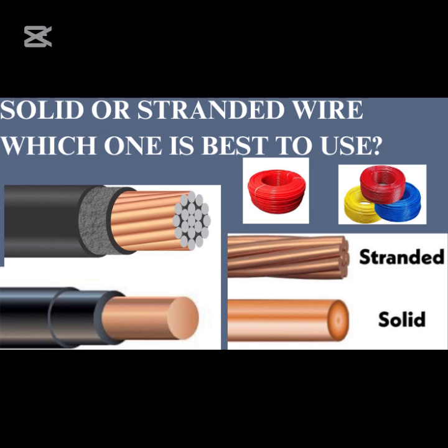If you're looking at durability, simplicity, and cost-effectiveness, solid wire is preferable. On the other hand, for complex projects requiring numerous bends and long-term flexibility, stranded wire is preferred. As you have seen, all the wires are good; the choice depends on the application and the factors mentioned before. I hope you're satisfied with the answers.